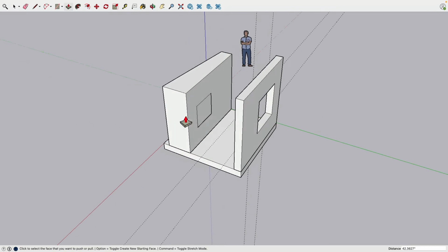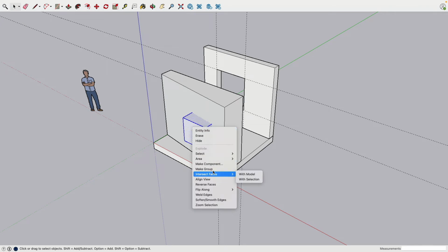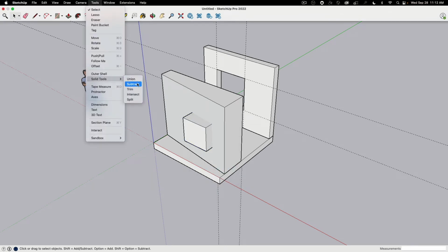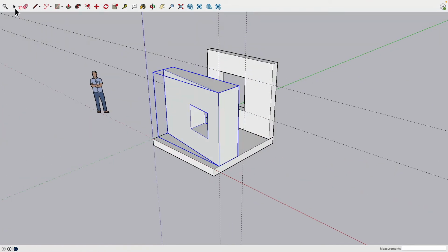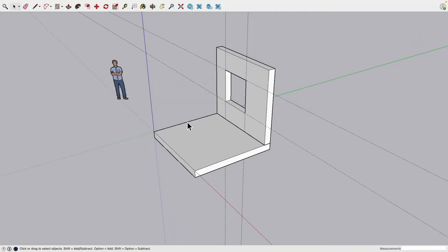So there you see, there's this. Push this out a little bit. I overbuild, make a group, and then I will use the subtract this, cut from this. And there we have it. Okay. So this is basically the two methods how you can build openings in walls. Either push and pull when the walls are parallel, or via the solid tools when they're not, or curved.